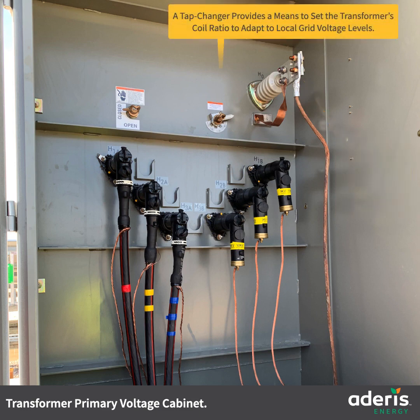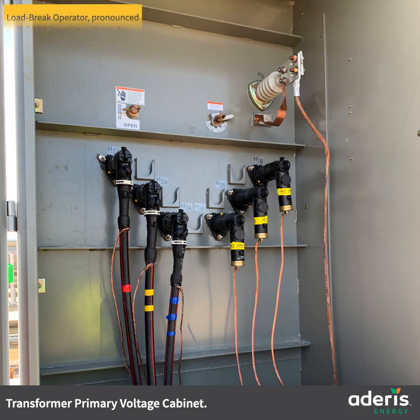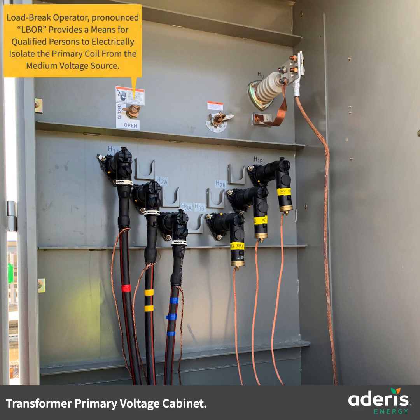A tap changer provides a means to set the transformer's coil ratio to adapt to local grid voltage levels. Load break operator, pronounced L-BOR, provides a means for qualified persons to electrically isolate the primary coil from the medium voltage source.